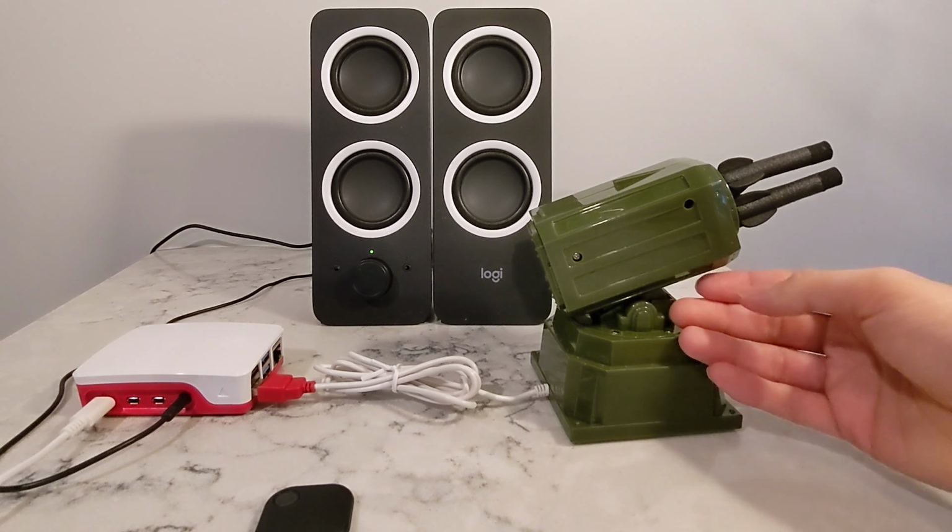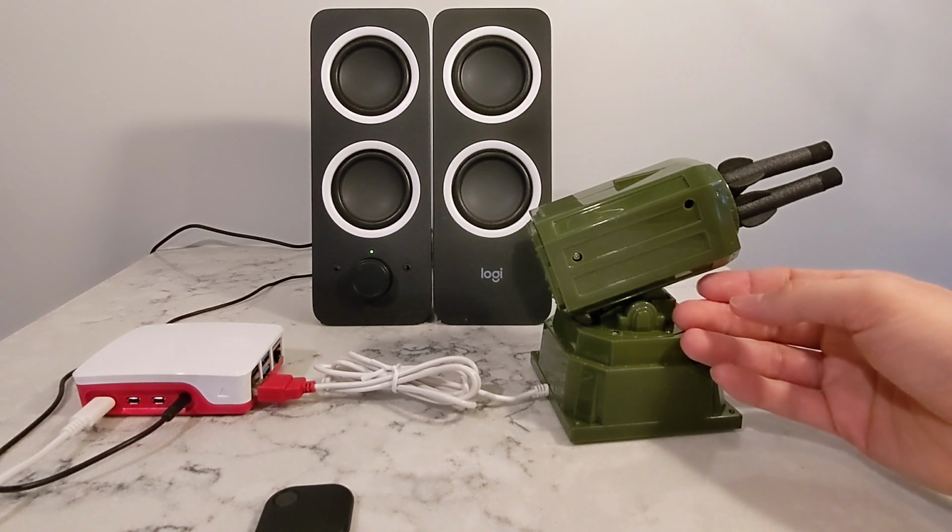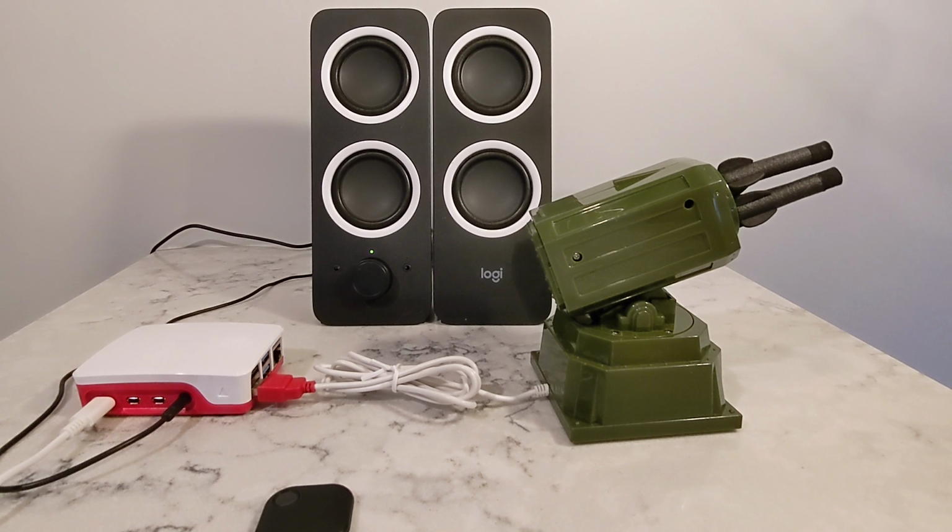While everything here is an off-the-shelf part, this build got off to a rough start. I purchased the missile launcher for another project several years ago, and it's been in storage ever since. However, after getting it hooked up, I quickly found out that it would move left and right, but it wasn't moving up and down, or the most important part, firing. I spent several hours disassembling it, and after some troubleshooting and eventually applying power directly to each of the motors, I was able to get it working again. Not sure exactly what the problem was, but it seems like the motors may have been seized up.